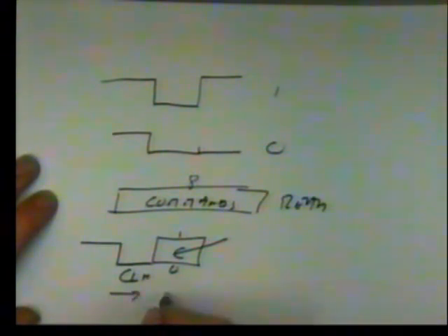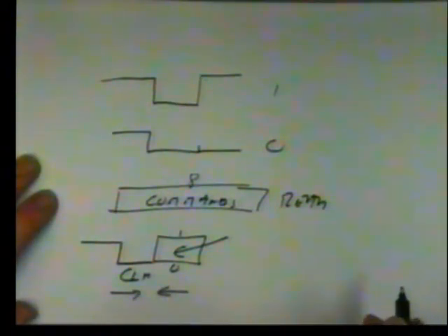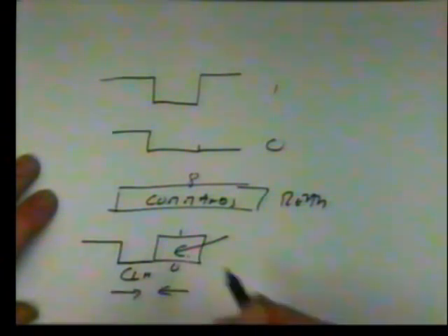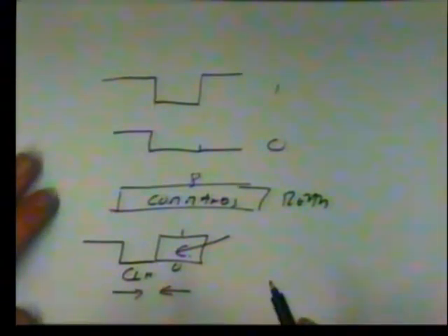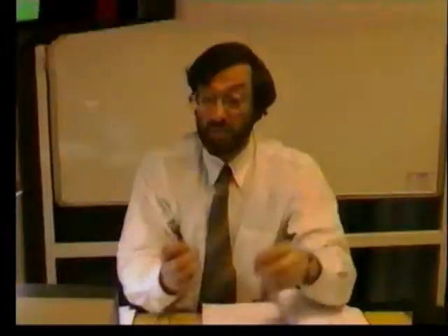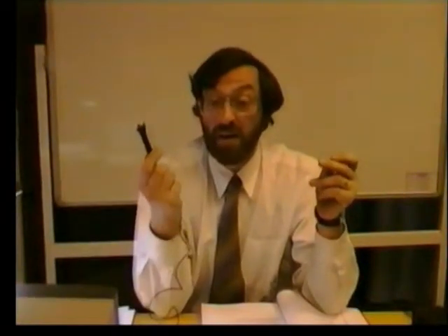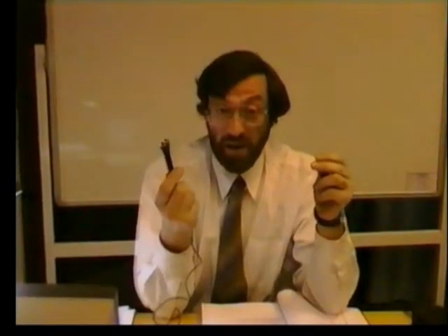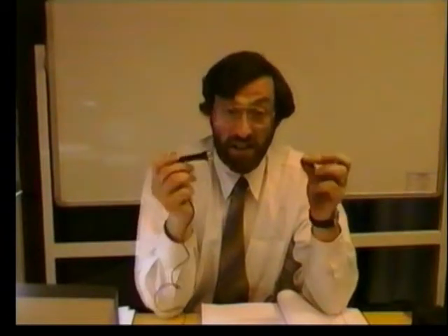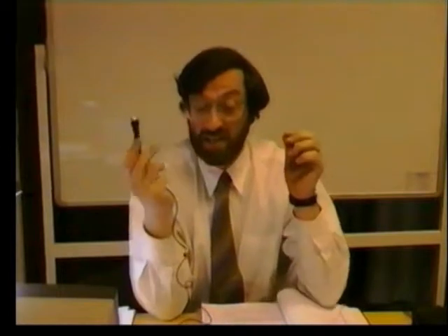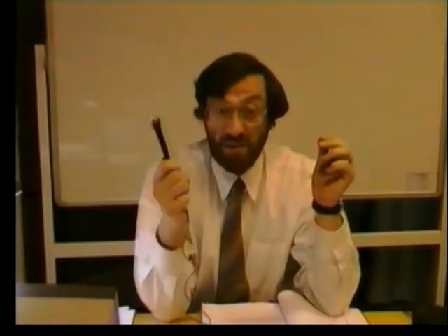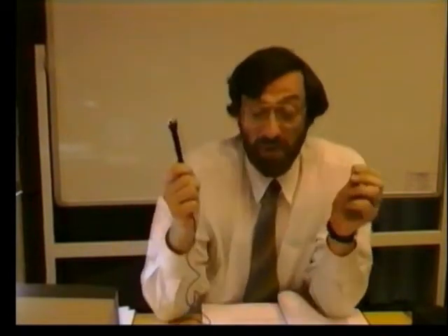So it outputs a clock and then reverses the half duplex line, and it reads back in the state of the line. So we have here a simple mechanism, single wire, half duplex operation. We combine the clock with the data, we can burst out 8 bits of data, and we can read back 8 bits of data. But remember, it's always the master device that outputs the clock. So let's have a resume.